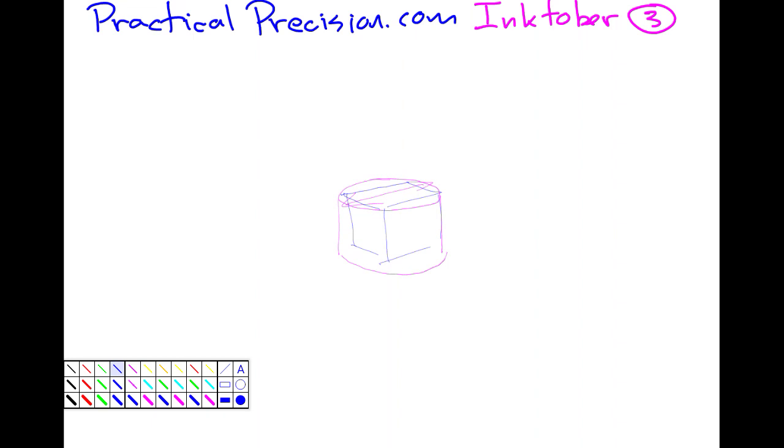So we're talking about the maximum volume that the machine can produce, and how would we decide what that will be? If we look at the top view of the machine, in general, we have some kind of space constraint that limits us to this long dimension L. If it's a cylindrical form, that's the maximum volume for that constraining dimension L. If we go with a rectangular or square form rather, then for that same limiting dimension L, of course, we have a smaller volume. So it would make sense to go with a cylinder in that sense.